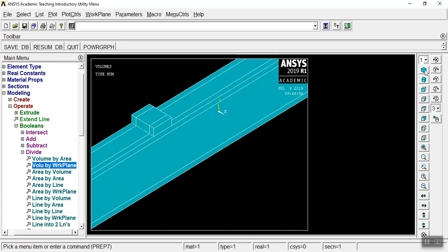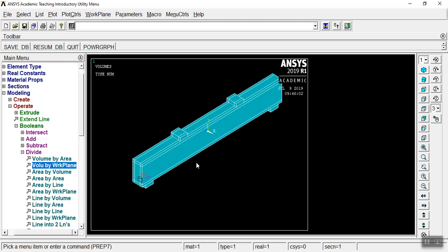Also, we can use the same way, but since I don't have any important stirrups in my case, I don't want to divide it by the position of the stirrup. But if you have stirrups in your case, you just move this local axis to the points where there is a stirrup.